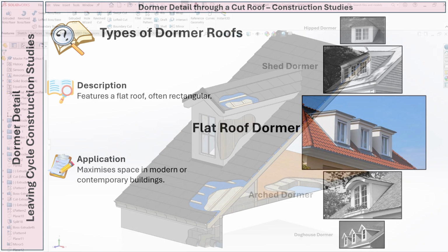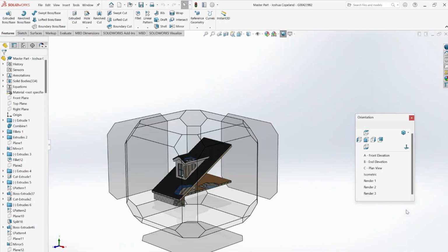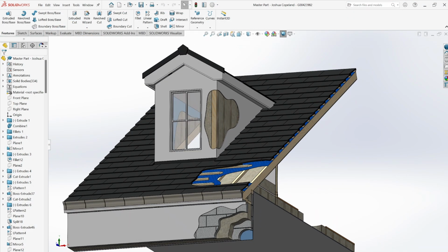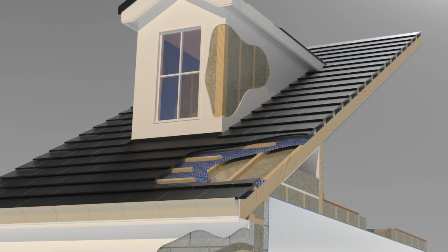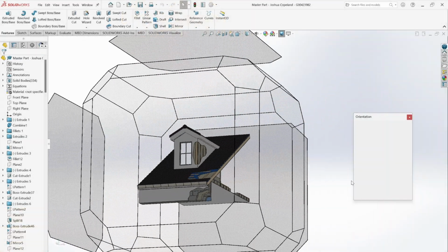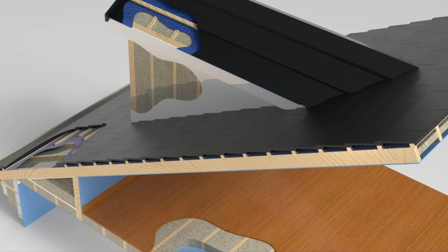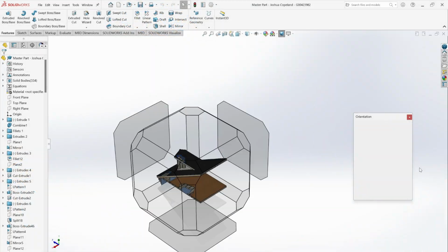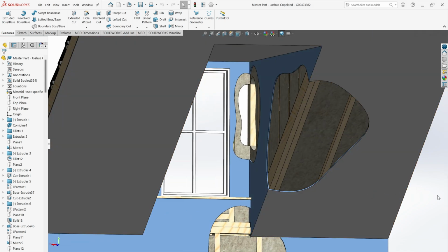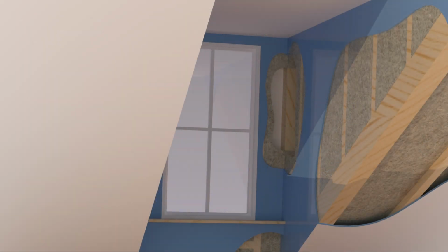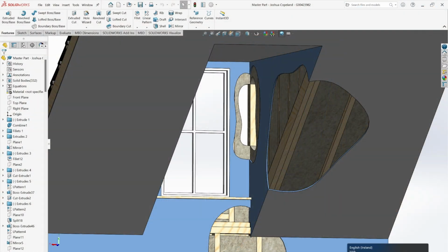Render 1 shows the passive block wall's internal structure: rafters, insulation, felt, battens and dormer vertical studs. Render 2 displays the dormer common rafters, insulation, felt battens, dormer ridge and 30-degree dormer valley. Render 3 highlights the dormer's internal structure featuring double rafters for weight distribution and internal render.